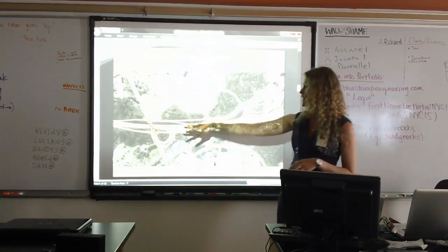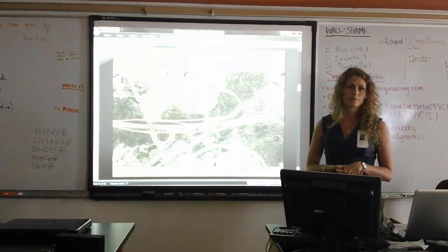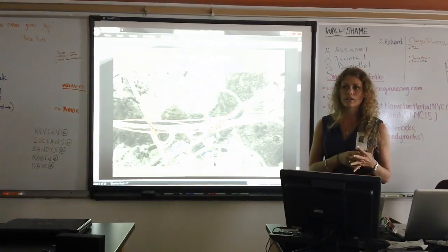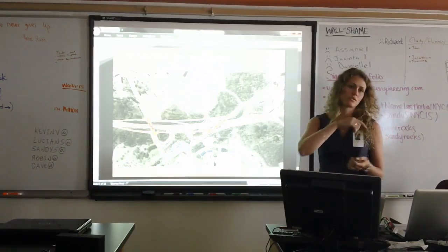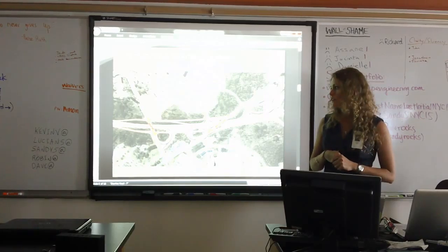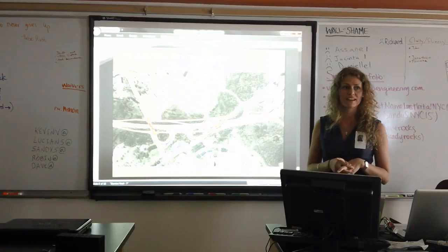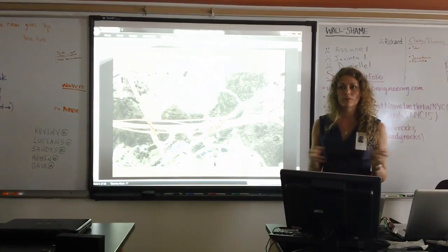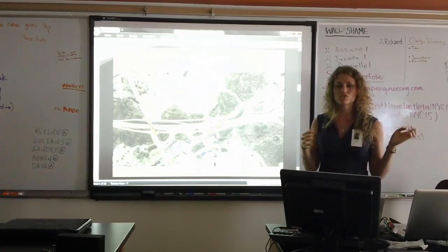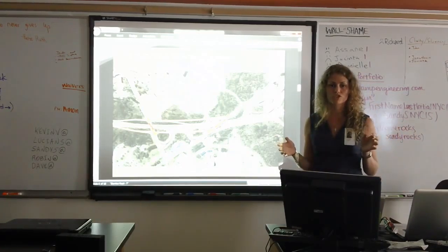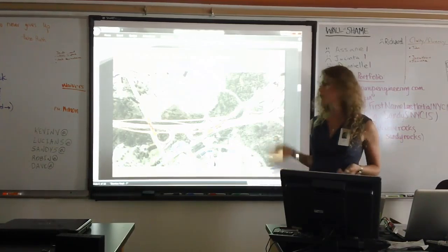So in these orange areas, we start off by doing traffic studies. Sometimes you might see some people out on the roads with a clipboard, and they track every single time a pedestrian goes by or a car goes by. That's how it used to be done, and people still do it for small projects, but today we use GPS, and I'm sure everyone in this room has a phone. A lot of times traffic collectors use the GPS on your phone to track not where you specifically are going, but to count how many people are going from point A to point B.